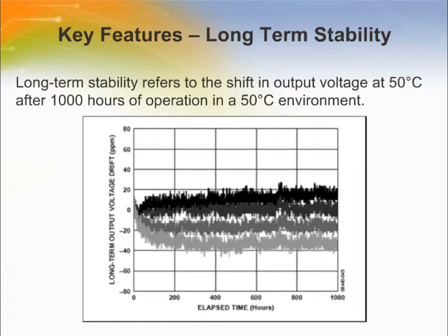may shift beyond the typical 30 parts per million specification at any time, especially during the first 200 hours of operation. For systems that require highly stable output voltages over long periods of time, the designer should consider burning in the device prior to use to minimize the amount of output drift exhibited by the reference over time.